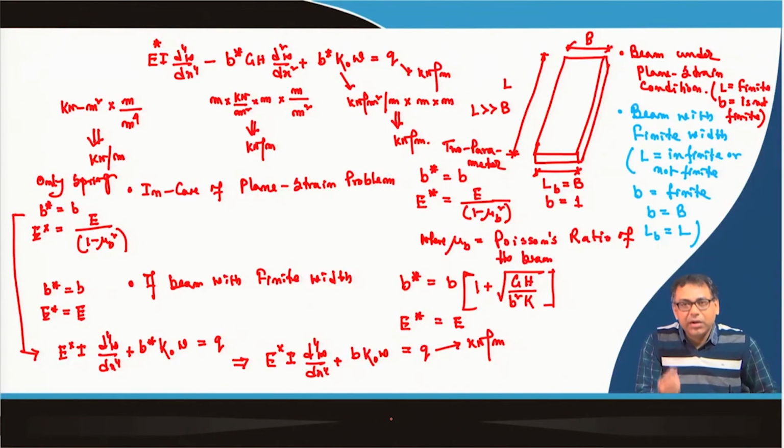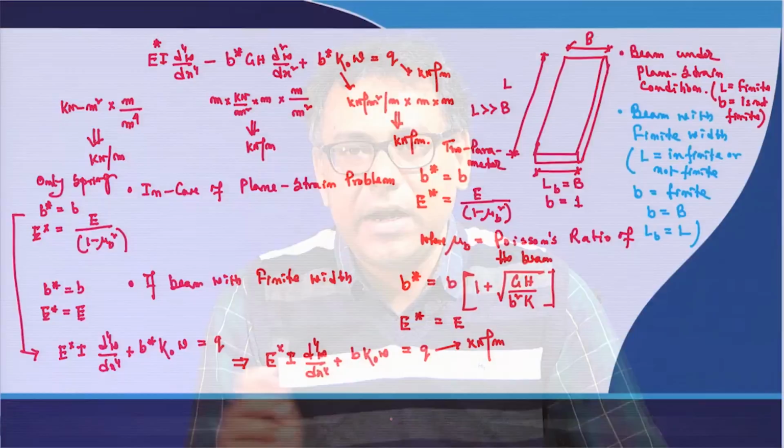But now, in the next class, I will discuss how I can solve this general equation for different loading conditions and different beam conditions, whether it is a finite beam or an infinite beam, by using a numerical technique, and I will concentrate on the finite difference technique only. So, in the next class I will discuss how these equations can be solved by using the finite difference method.